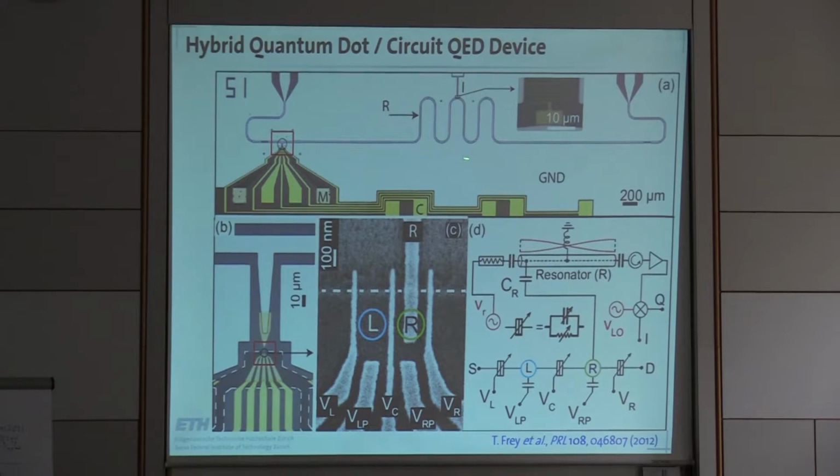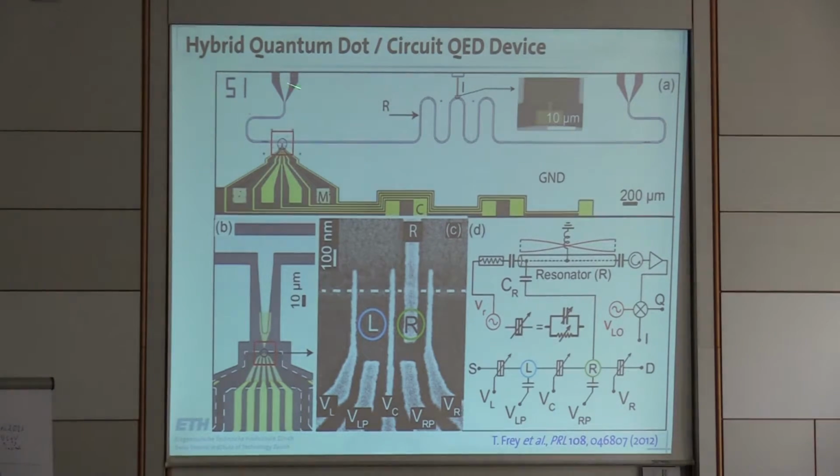The resonator itself should be floating in principle. At lambda half, it's floating, but it is connected through this little inductor to a bias point, which you could bias in principle. But this couples to a node, so at DC it's grounded, but at the AC frequency, at the resonator frequency, it's not grounded.